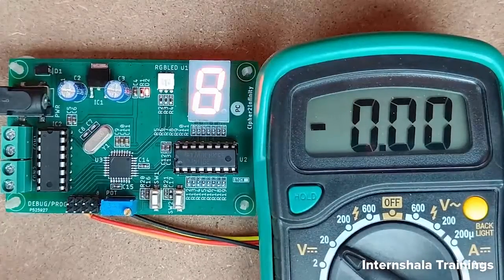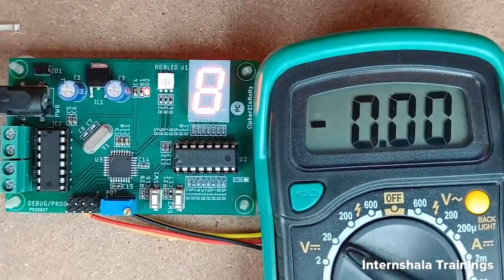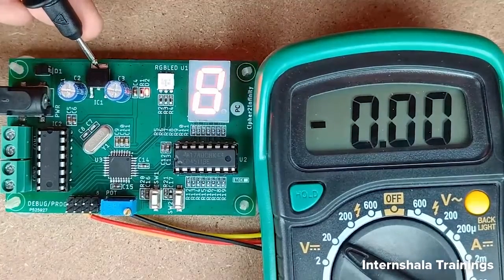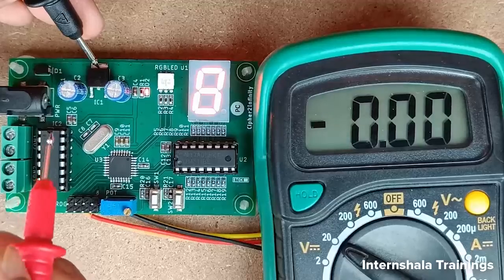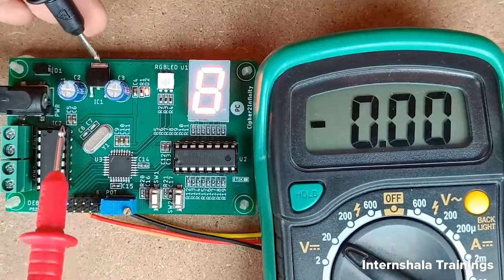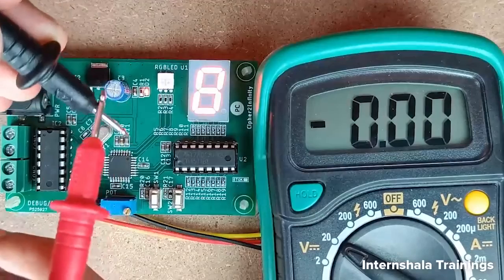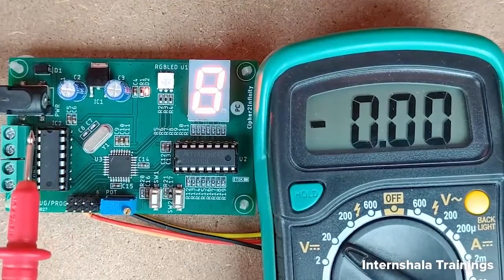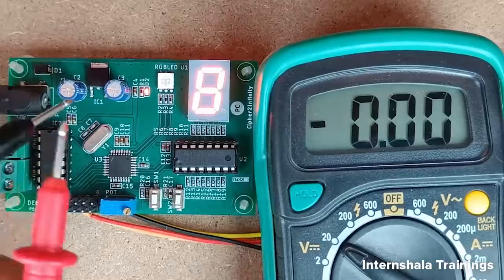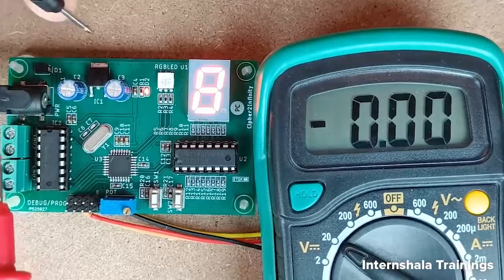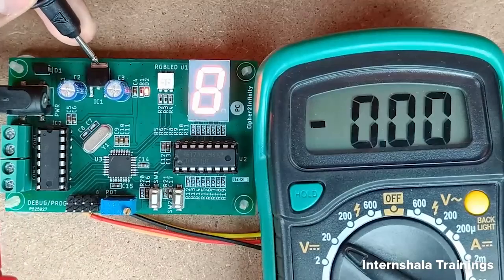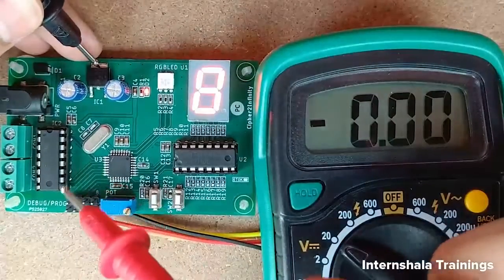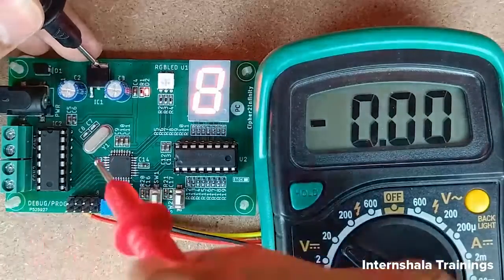After that, I'm going to connect this negative terminal at this point. I'm going to connect it to the ground, or the plus 5 volt ground tab of this 7805. Or you can also connect the negative terminal of the multimeter to the power source. I have the lab bench power supply, so I can connect this negative terminal there also. But let me connect this negative terminal at this point, and let's check whether 5 volt is available on all the pins of the microcontroller or not.